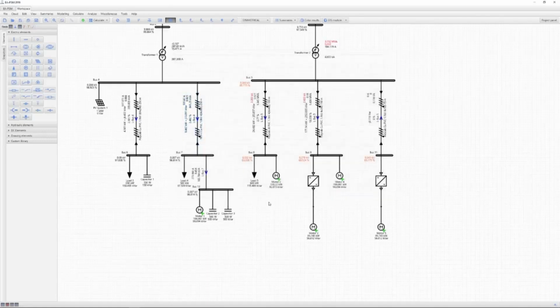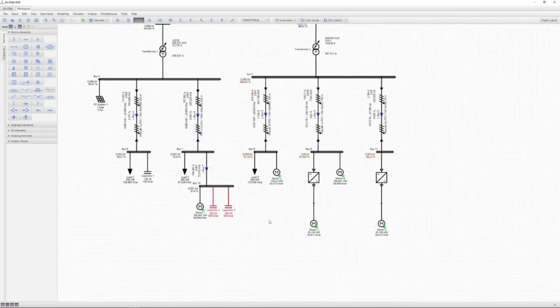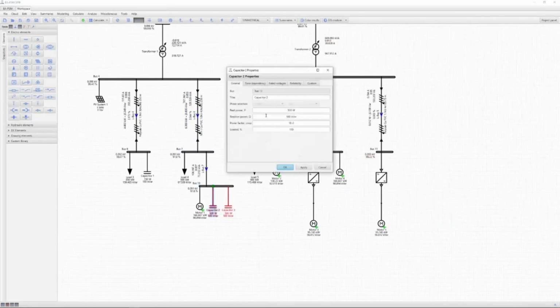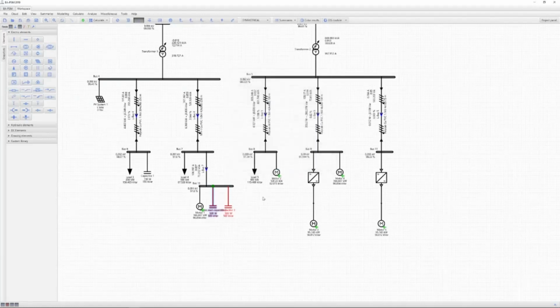So as we can see, now we have solved the problem of the cable ampacity rating and the voltage drop levels in this specific part of the scheme. And yeah, now we have solved the problem of the voltage fluctuations and the cable ampacity. But we must remember, these capacitors should be named motor start capacitor, because we only use them when we're using the motor start. We're gonna put the same here.